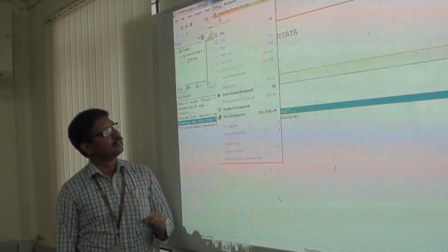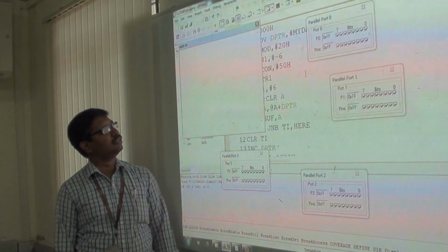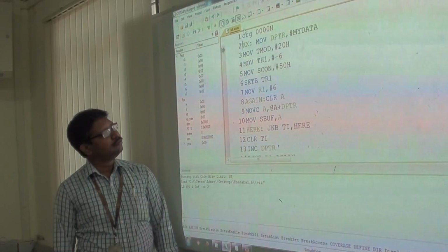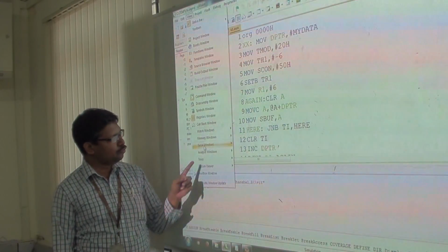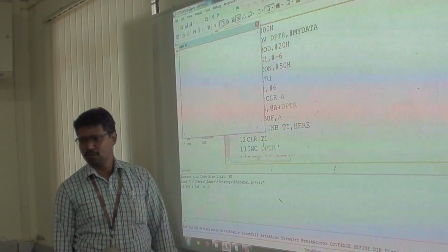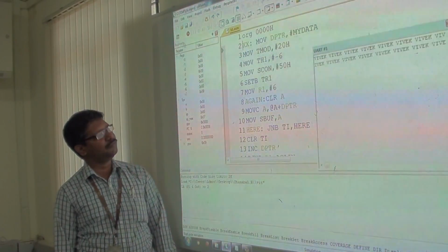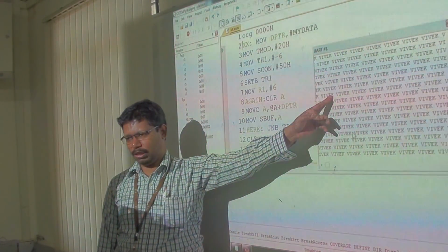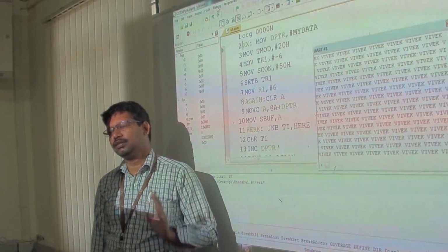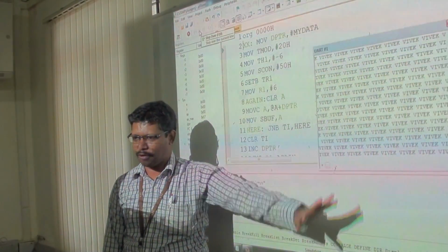After that, we are going to start the debugging session to visualize the output. For visualizing the output, just view the serial window. Which port? UART1, you select. Okay. So note down: view, serial port UART1, and keep it in continuous run. If you do this, you can observe the output in the Keil software itself. The same output we are going to observe in the hardware. Okay, so this is the procedure for getting the output in the software simulation.